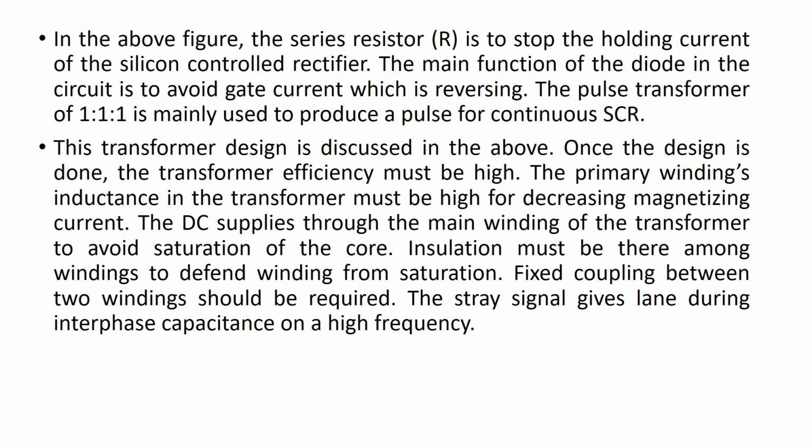This series resistor is used to limit the holding current of the SCR. The main function of the diode is to block the reverse gate current. The transformer design is discussed here.